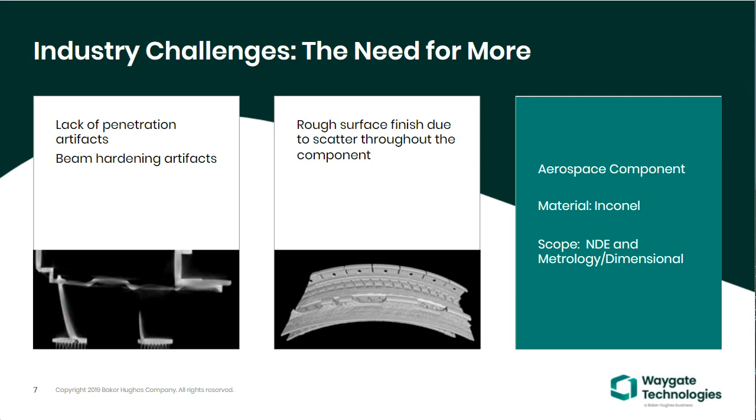Here's an aerospace component made of Inconel, which requires NDE and metrology analysis. We scanned it on 450 kV, what's possible. You can tell that there's a lack of penetration. There are artifacts, beam hardening artifacts, and rough surface finish due to the scatter. It really isn't good enough with the current technology.